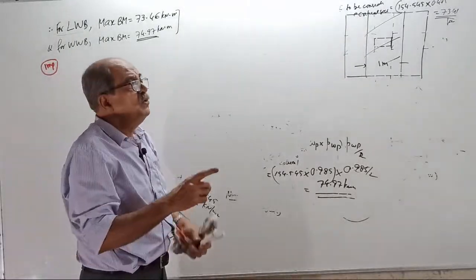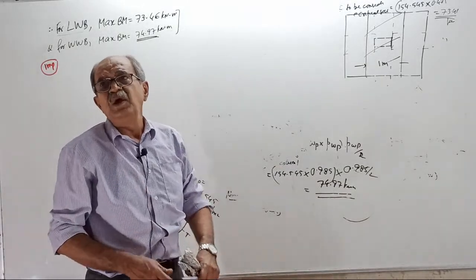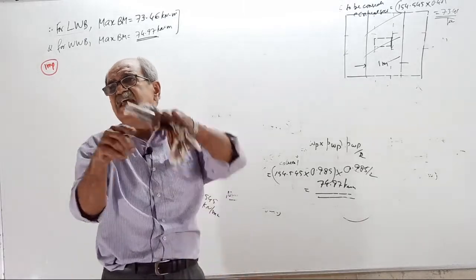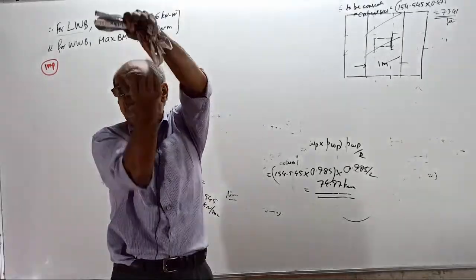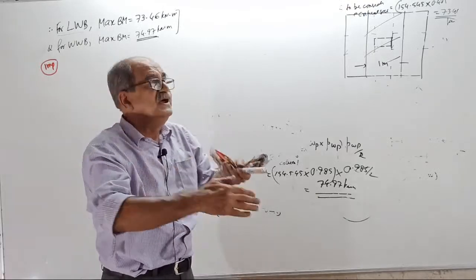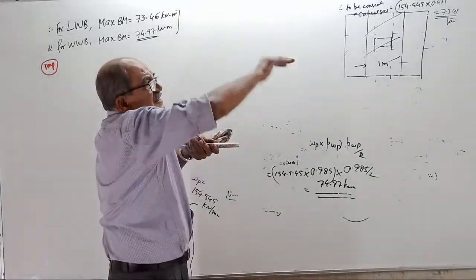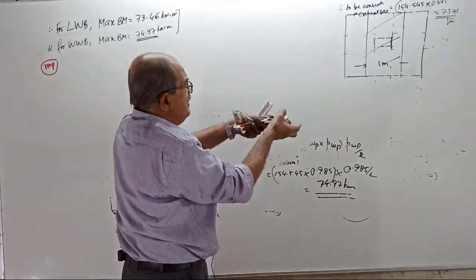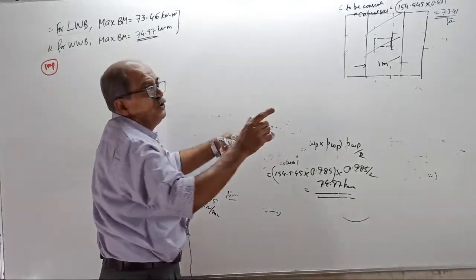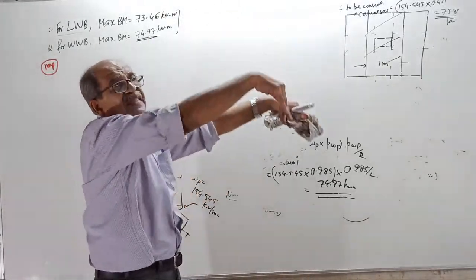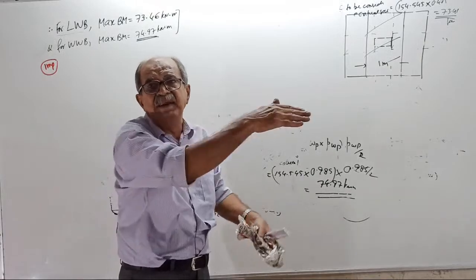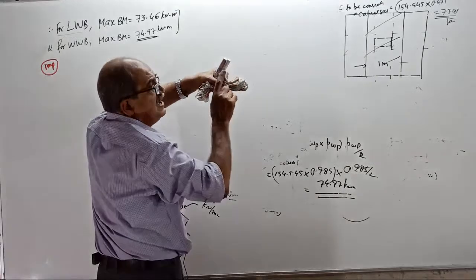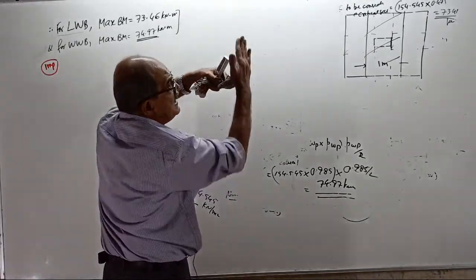Now, in the theory, we have the maximum BM. Based on maximum BM, you find the depth required. Structural depth: when bending is this way, the thickness of the slab is the structural depth. When you do pressure calculation, then structural depth and width are planned dimensions. But when you consider bending moment and shear force for the footing slab, structural depth is the thickness of the slab.